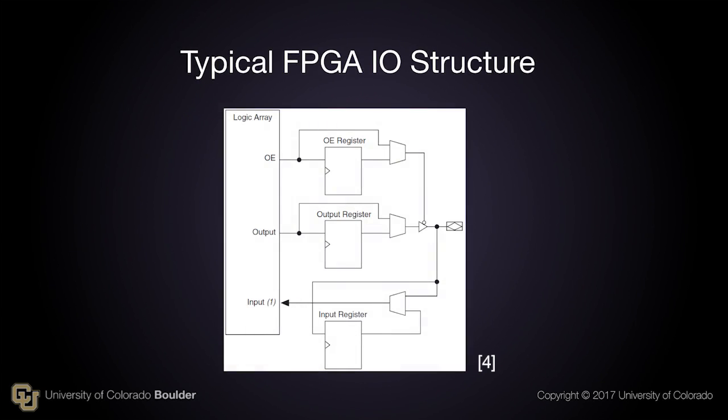Here is a simplified version of the circuitry at a typical FPGA I/O pin. When driven by the external source as an input, the signal propagates to the input register or can bypass it directly to the FPGA logic fabric. When configured as an output, the pin can be driven directly by a register, and the output can be enabled or disabled to create a tri-state bus output.